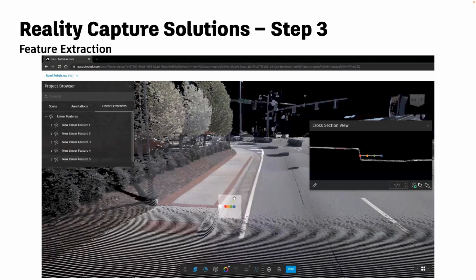And now I can actually say this is what I want to extract, and it shows you those 4 dots. Those are the vertices for your lines. So I'm setting up the template here, like back of curve, top of curve, bottom of curve, lip of curve. Anything you want, you can actually specify. In this particular case, it's a curve. I can specify, and I can add the tag information.